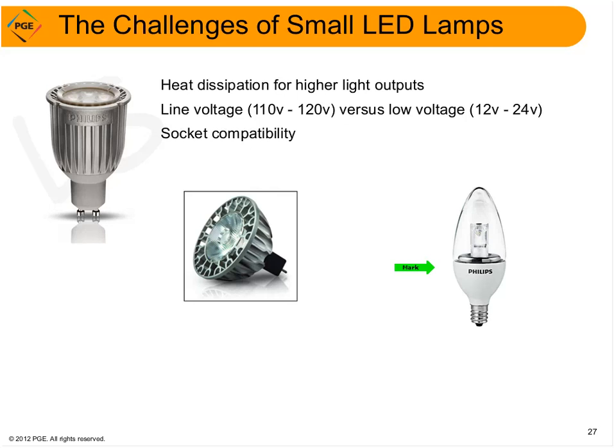Currently, you can easily find LED MR16s that will replace 35-watt halogen MR16s, but it's more challenging to find ones that replace the 50-watt halogen MR16s. But more of these are coming to market. You can find them, but there's not as many as the lower wattage.